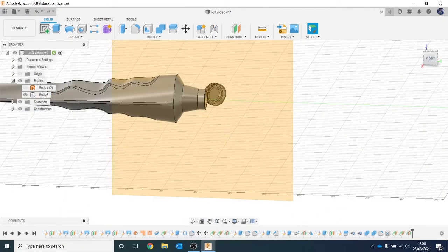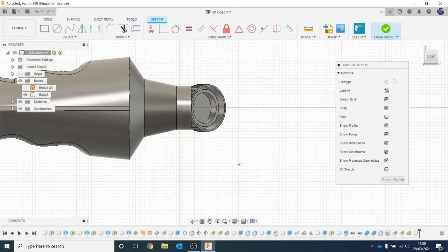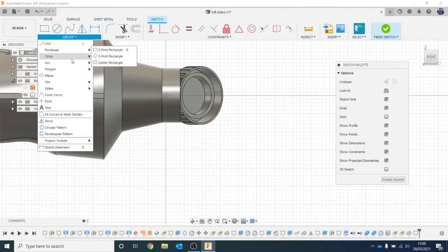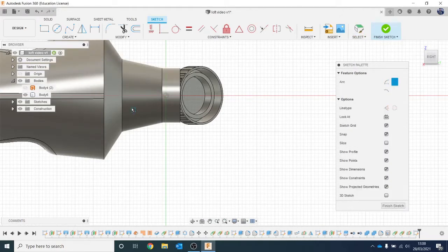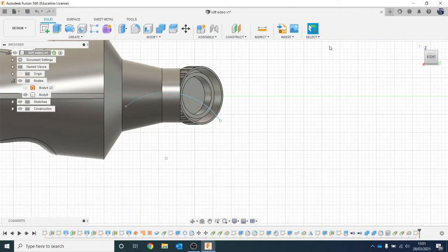Okay, so we're going to create a sketch. And we don't want to go out a lot, just a little bit to, again, make it look more real. When we come to rendering things, you want it to look realistic. So we're going to go to arc, 3-point arc, and I'm going to just start in here a little bit. Just click out a little bit and come up. And click escape, so I've got that. Then let's click on finish sketch.